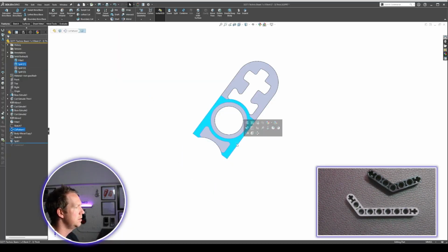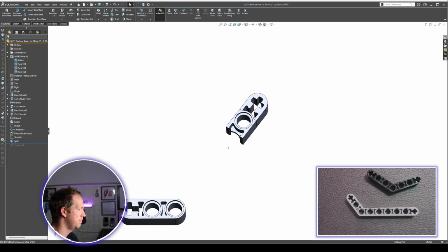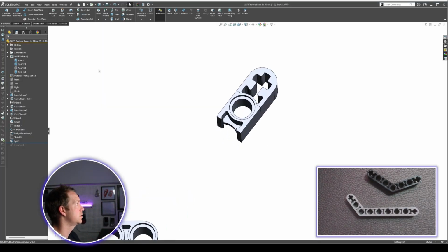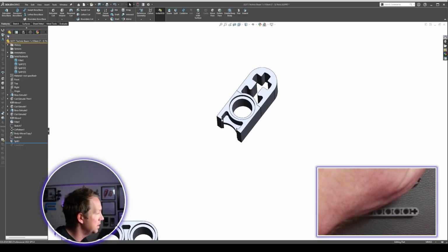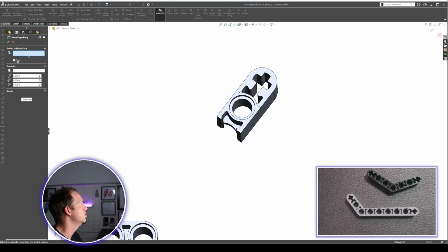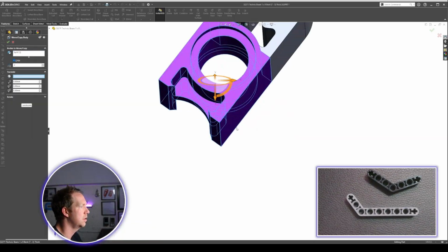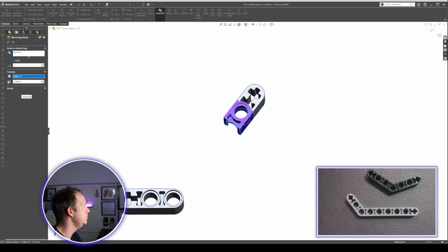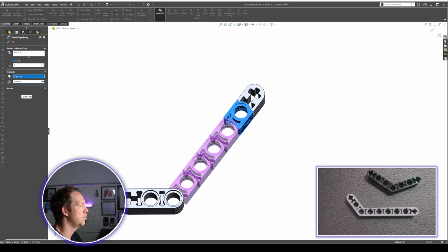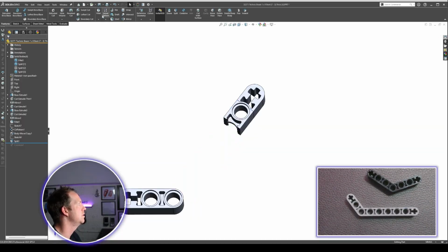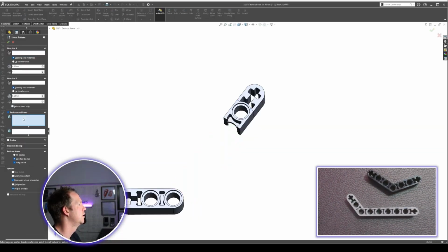That first solid body I'm going to hide. I can delete it later. It's the middle solid body here that we want to pattern. Now we could do a move copy body like I did earlier. Move copy feature does have the ability to do multiple copies. So I could do this body, and I could do 4 copies of this body in the same direction, use an edge. This is one way to do it, but this feature is not as strong as the linear feature tool. Linear feature tool is the proper one to use in this kind of situation that we're doing.